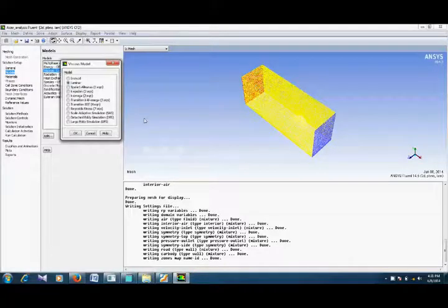The viscous models, you should know about these things. They are turbulence models, and as our flow will be turbulent, we have to select one of these, and each and every model is appropriate for certain flow conditions. The SA model, Spalart-Allmaras model, is a one equation model for such types of flows as external aerodynamics.